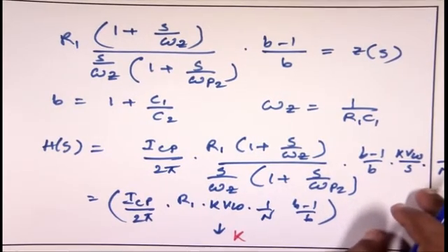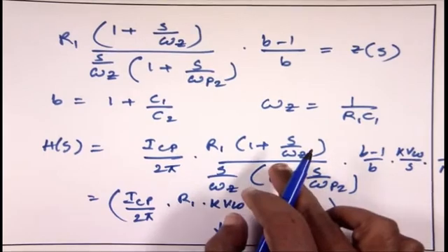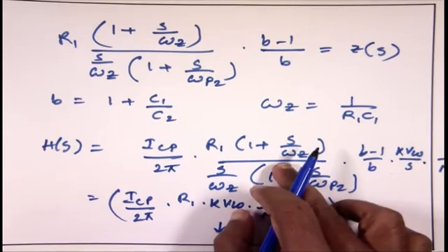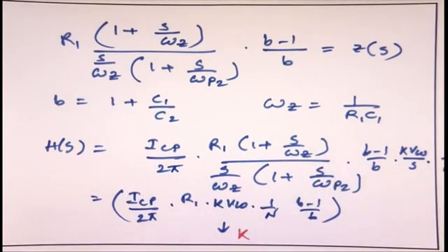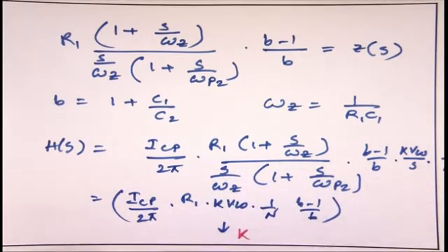This is the most dominating factor which will give you instability, because a pole location at the origin will always give instability, unless you are adding some zeros. So you have that zero here, implemented through the resistance. I am not going into those details. That is why you are using R1, the resistance, to create a zero so that you will not have a double pole at the origin. If R1 is 0, omega Z will nullify, and ultimately it becomes an all-pole system, and then the system will be unstable.